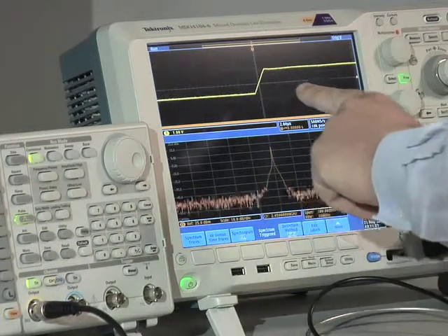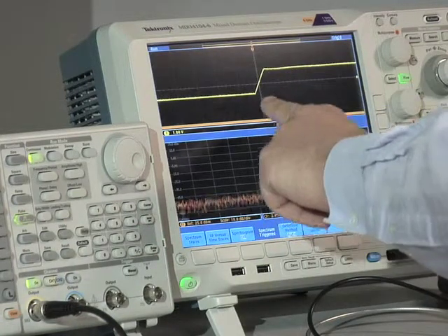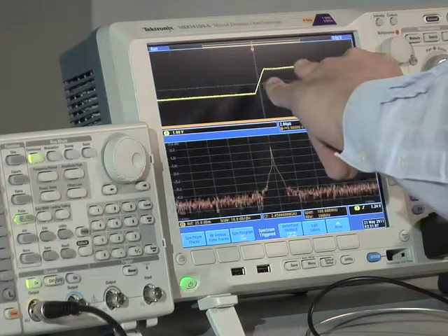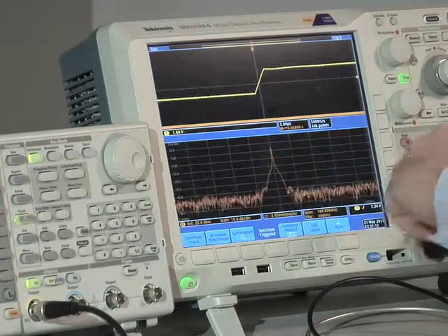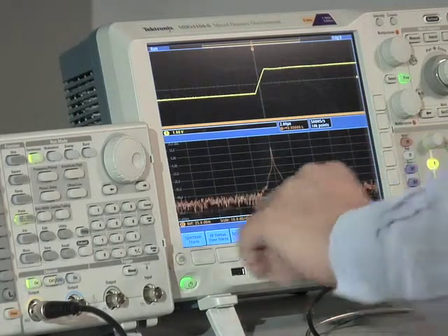So that fairly clearly illustrates the consequences of changing the rise time. Obviously the PA turns on more slowly, but at the same time your spectral purity, your transient spectral purity, improves dramatically. So what we've shown here today is the ability of the MDO4000 to very quickly and easily demonstrate the turn-on characteristics of a power amplifier, both in the time and frequency domains in a time-correlated fashion.